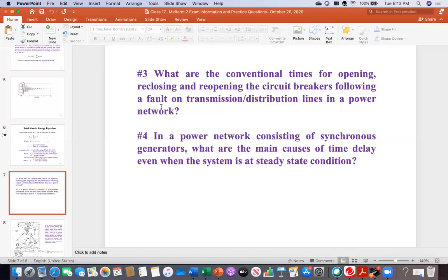Now, as I was telling you, MLGW reclosed after 45 cycles after opening the breaker. Once I had a chance to ask them, and they said 45 cycles. But some countries and power networks depend on 40 cycles, 45, 50 cycles. At the latest I have seen 60 cycles, and the earliest is 30 cycles.